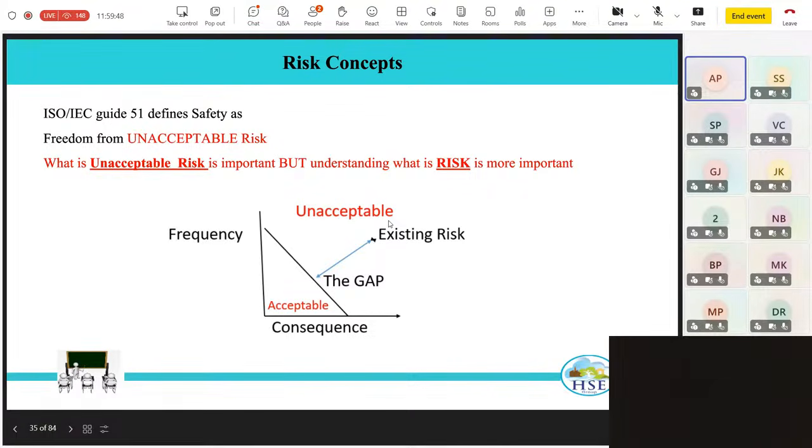Once you have this commonly used concept of functional safety, there must be a proper definition of it. CCPS is the Center for Chemical Process Safety. They have given a very beautiful definition, which you can please listen carefully and understand. Functional safety is the part of overall safety of a system or a piece of equipment that depends on the system or equipment operating correctly in response to its inputs, including the safe management of likely operator errors, hardware failures, or environmental changes.